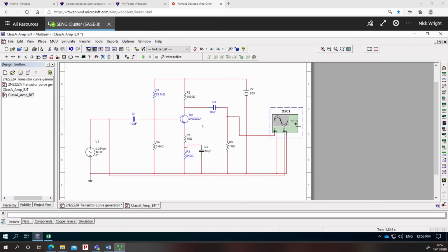If you look on the screen, this has all the components that we've discussed in the other parts of this course. At the center of it obviously is the transistor, and here is the collector resistor. These are the emitter resistors at the bottom here. These two resistors here are the biasing network, and then we've got a signal coming in, a very small AC wave. We've got our capacitors here at the input and at the output, and this is the so-called bypass capacitor.